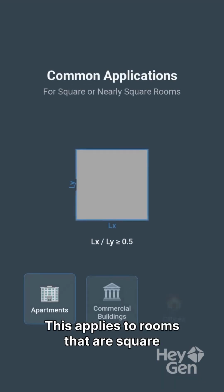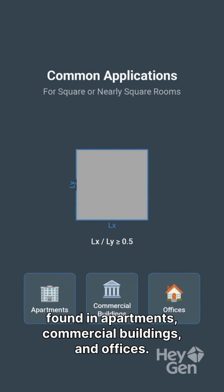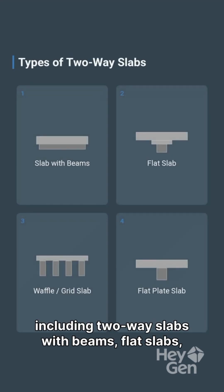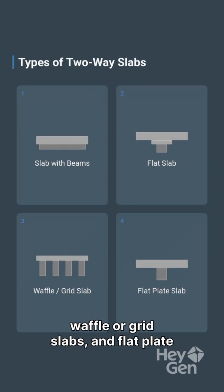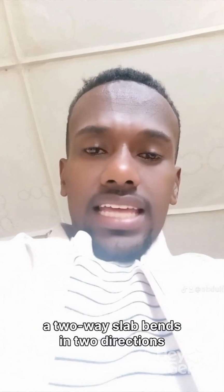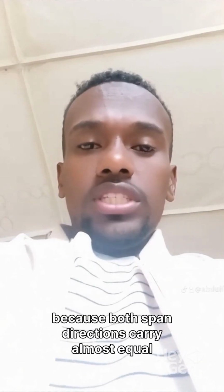This applies to rooms that are square or nearly square and large floor areas found in apartments, commercial buildings, and offices. There are several types of two-way slabs, including two-way slabs with beams, flat slabs, waffle or grid slabs, and flat plate slabs. A key point to remember is that a two-way slab bends in 2 directions because both span directions carry almost equal load.